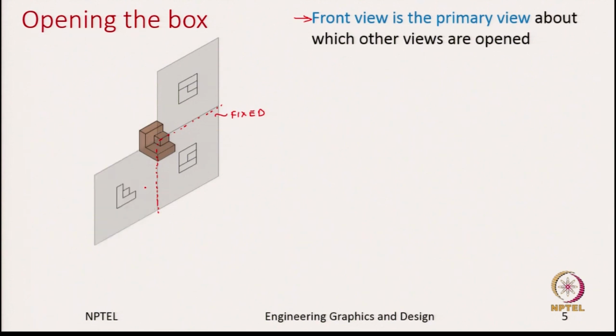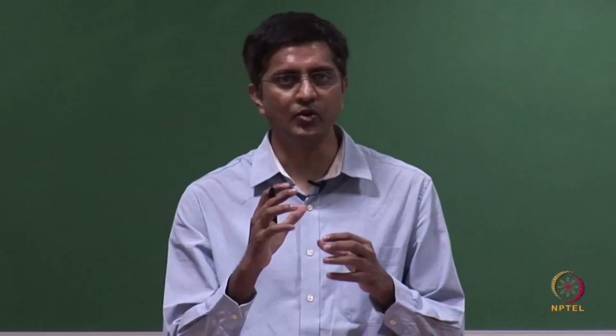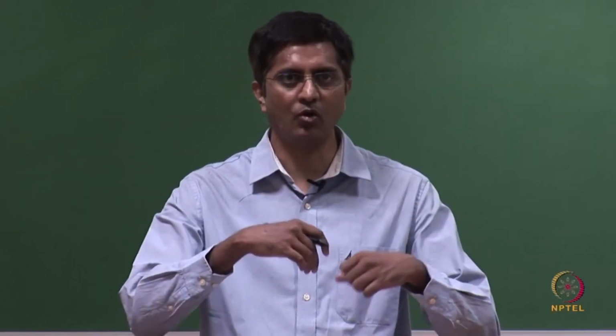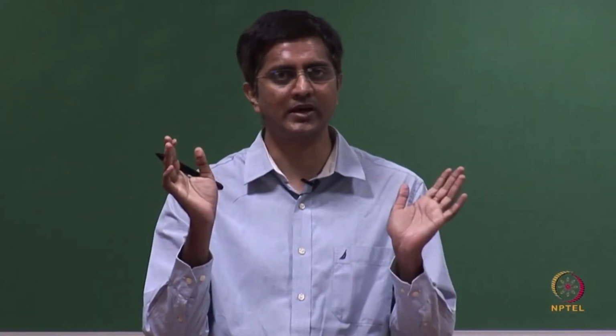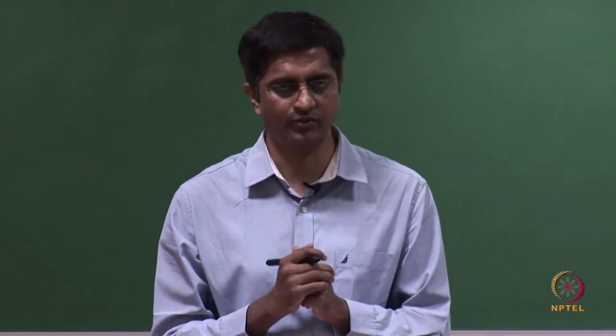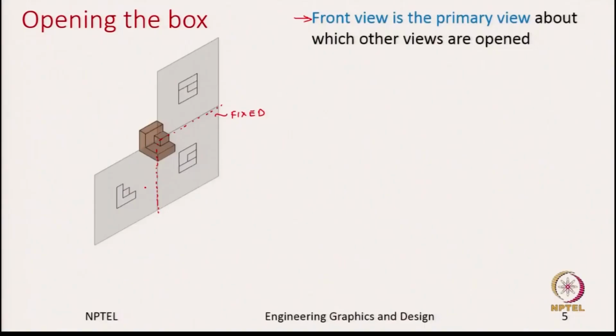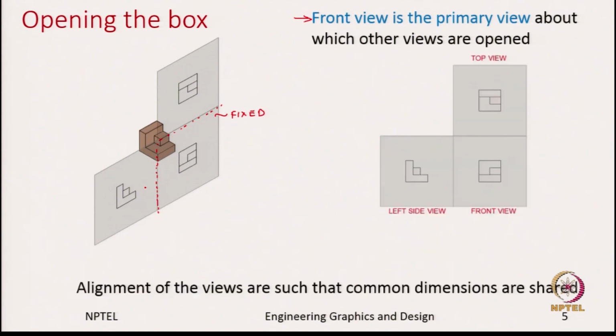So, what we are able to do is both the top view and the side view, we have opened them such that they are in line with the front view. Now, all of them are in a plane, and this is how it looks when I depict it on a piece of paper. So, where you have the front view, top view and left side view.